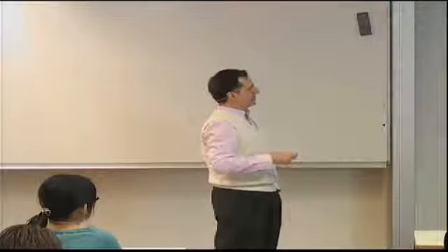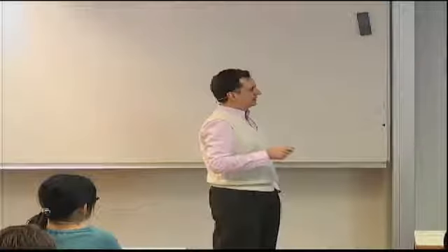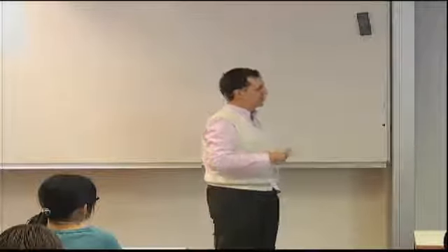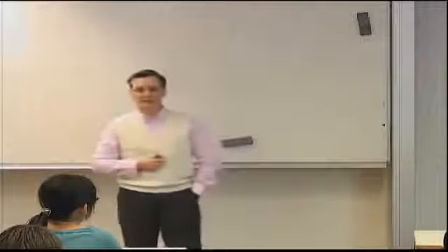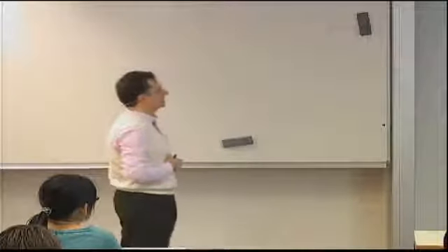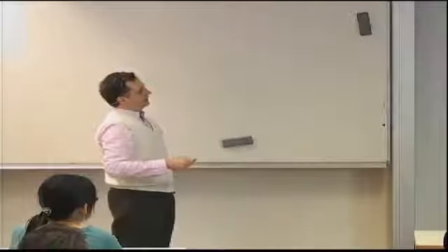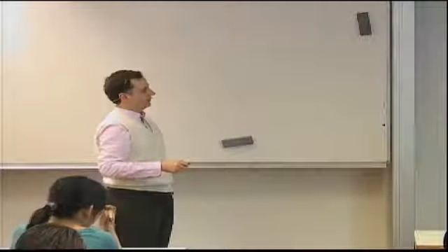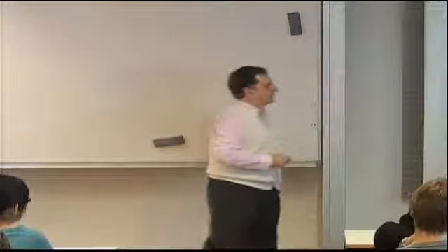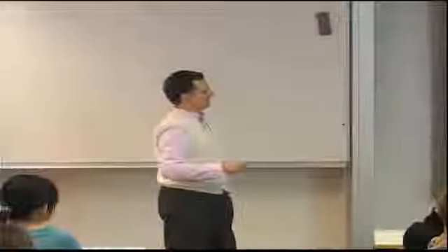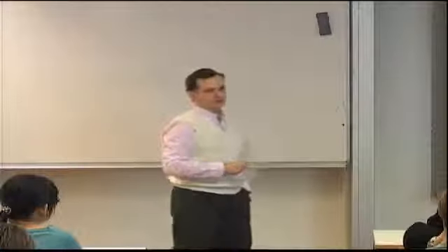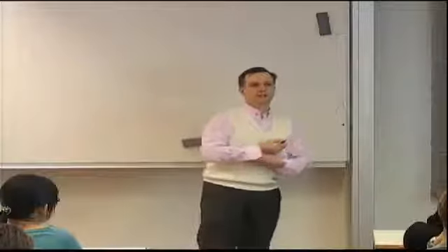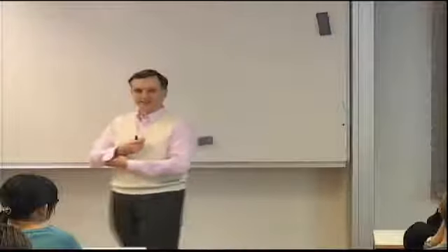So the reason I wrote in the previous slide all the A matrix and D matrix properties was because I need them to calculate these quantities that go into this. And the buckling load given by this expression, when I calculate for laminate A, I get it to be 718 newtons, and for laminate B, 536 newtons. So there is a significant difference of 25% here.